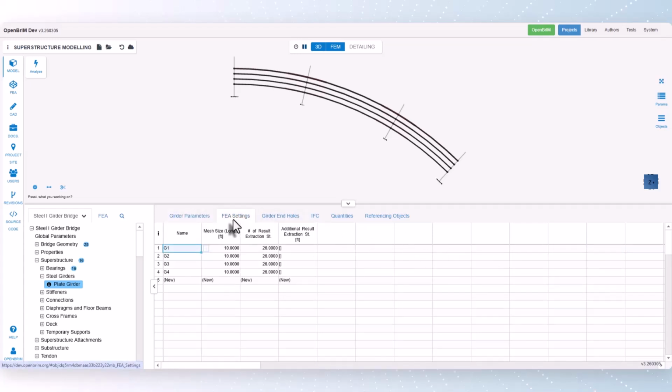The mesh size parameter specifies the maximum distance between nodes in the longitudinal direction, as defined by the longitudinal mesh size. In most cases, a smaller mesh size may be applied, depending on the locations of bracing, deck pouring or removal, or changes in section geometry.